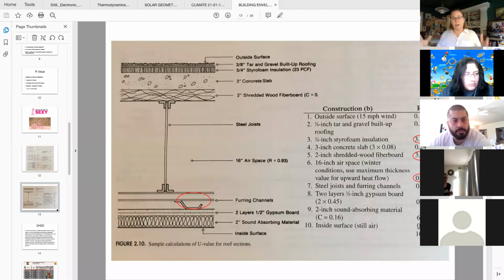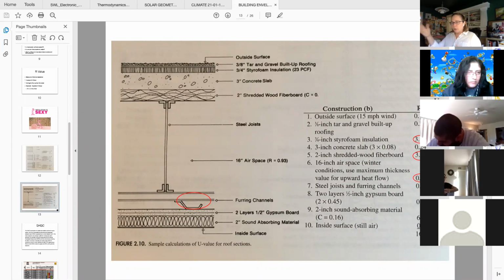So that's going to take a lot of footprint. And typically you're going to need larger land area for the bigger footprint. It makes your envelope a little bit bigger, which makes some of your material costs go up. So there's all of these different factors that come into play on where is that sweet spot of how much insulation to use and how thick your assembly is going to get in trade-off for your performance of your building.